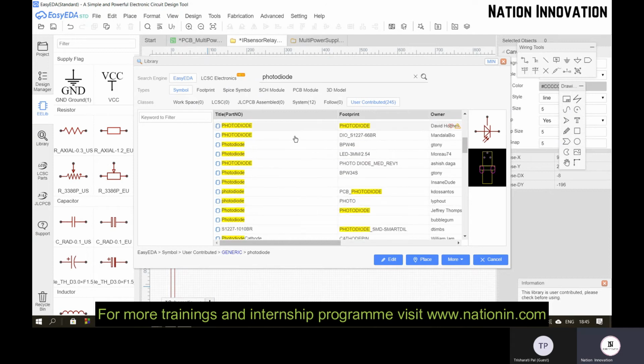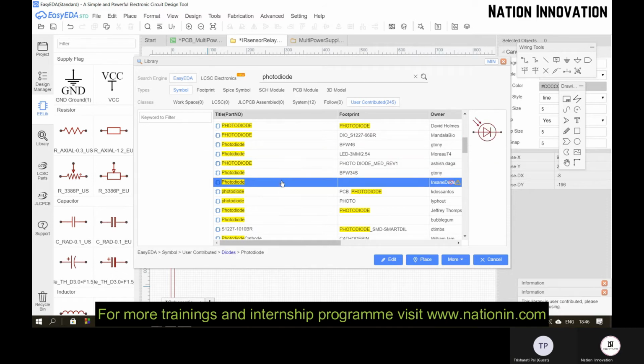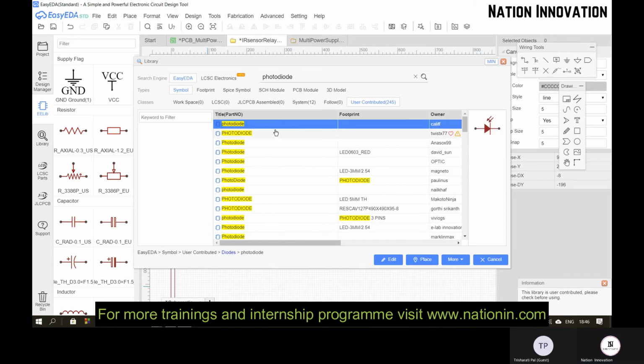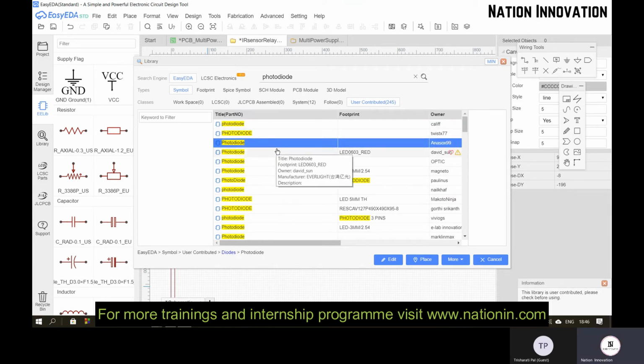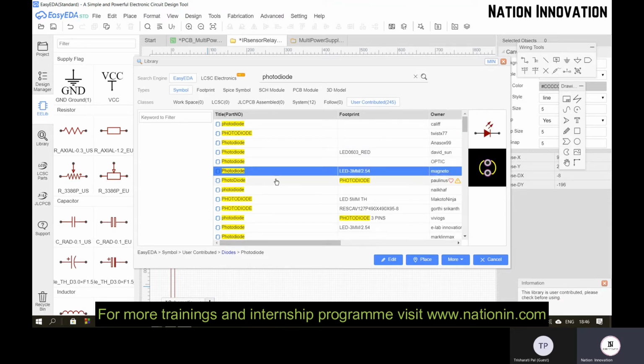So select a through hole photodiode. These are all symbols; they have no footprint here. So I'm searching for a photodiode which has footprints. This one has a footprint and it is a through hole component, so I am selecting it.